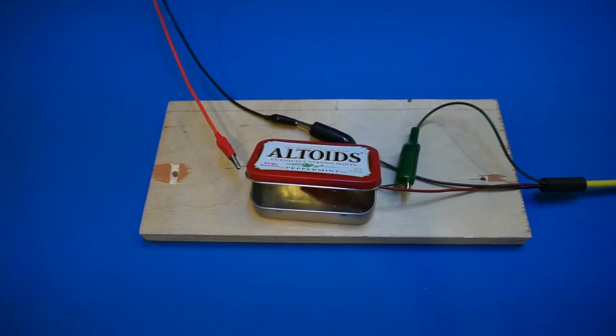And here is our experiment set up. By the way, the reason I need to put the whole thing on a piece of plywood is because this surface is a dissipative surface, and it in fact has a resistance in the giga-ohm range. So that resistance itself would affect the measurement and the current flow of this sensitive measurement. So ideally I should put the whole thing on a stand with extremely high resistance, but I think a piece of plywood should be sufficient for this experiment.